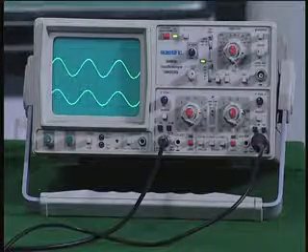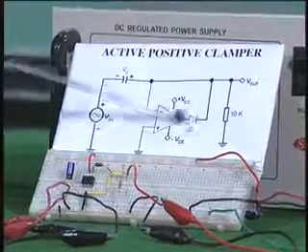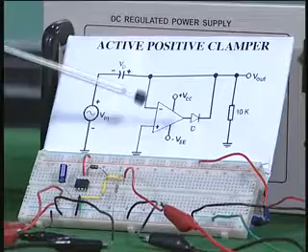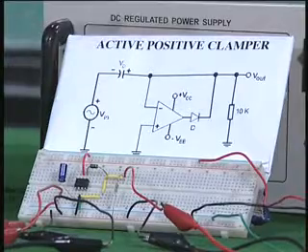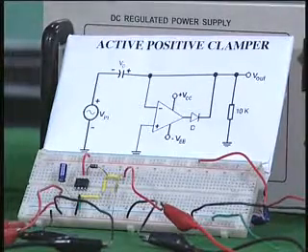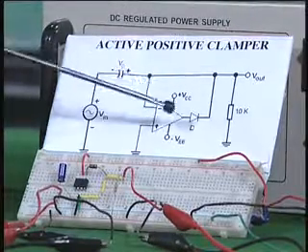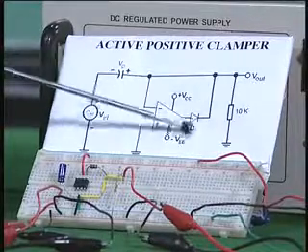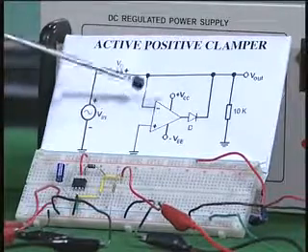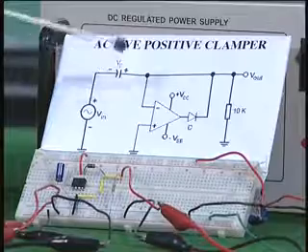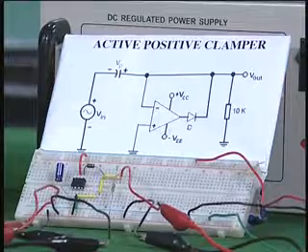Now if I want a negative clamping, all that I have to do in the circuit is invert the diode here, and then you will get a negative clamping, that means the whole signal will move to the negative side, the clamping will be done with reference to 0 and the peak will be on the negative side, just as we saw now on the positive side. You can go to the negative clamping by just interchanging the diode, turning through 180 degrees, and then redraw the circuit, you will be able to get a negative clamping. The positive clamping and negative clamping are also very useful in different applications in electronics.